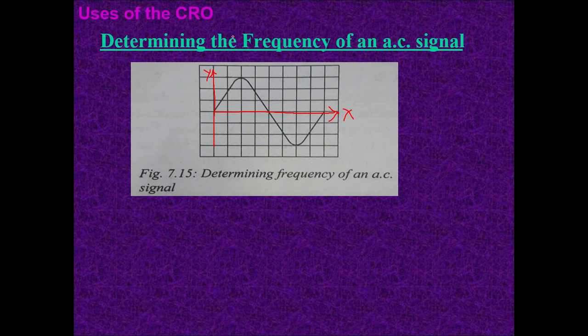Now let's basically explain what I've simply said. So the time t will be associated with the time base, whereby the time base is associated with the X plates, and the X plates, because you're using the terms of the graph, shall be the X values. So the X values here, if I'll have the time base being a particular value, they shall be given in, for example, let me say seconds per division. So each of these divisions shall represent that specific value, and you shall be able to calculate them the same way you usually calculate the period of a wave, and I believe that will be much clearer when you get to examples.